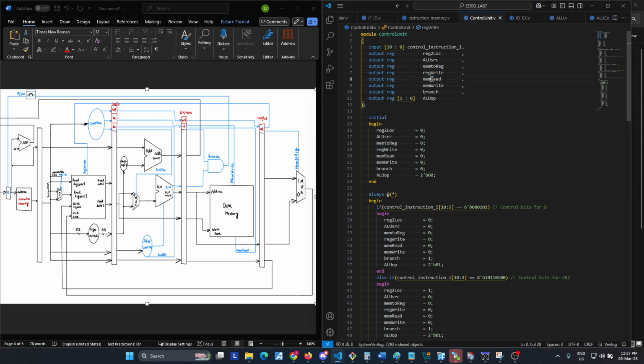Finally, we have reg-write, memread, and memwrite. All these 3 signals. So memread and memwrite will tell us whether the data memory needs to be accessed or not. If the memwrite is 1, we'll write into the memory, for example, for store words, essentially. And for memread, we'll have the data from the memory out into the pipe and then towards the register file for our operations to follow.